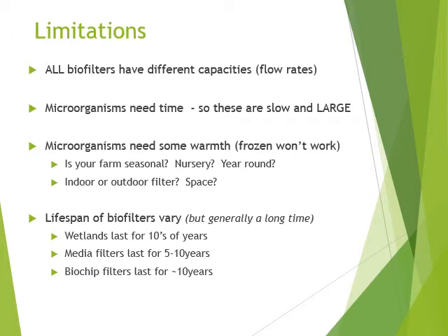The other thing is microorganisms need warmth. There are certain temperatures that are required in order for them to function, right? So in the winter, if it's freezing and your system's outside, it's not going to work. So is your farm seasonal, right? Different systems are applicable to different farms. Nurseries are growing in the summer months, so it's not a problem to have an outdoor biofilter. Whereas a year-round growing facility would have to have either one in the ground that's sufficiently warm so it doesn't freeze, or one built inside the farm, which might look very different. So that comes into play when you're talking about space. Those are important considerations.